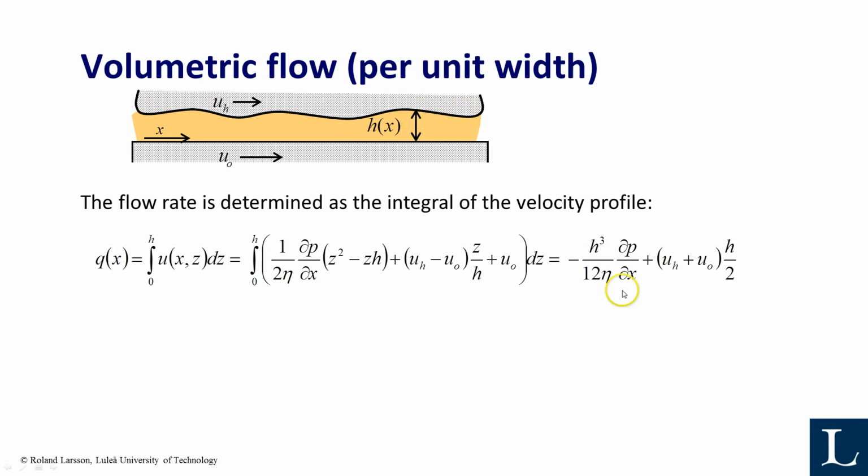So h is a constant, viscosity is a constant because we assume that the temperature is kept constant. The speeds are not constant. One surface is stationary and the other one is moving with the speed of the piston. So that's x dot actually. And dp/dx, that's the pressure gradient. So that's the change of pressure from that end to that end. And we can assume that we have a linear decrease of pressure from here to there.